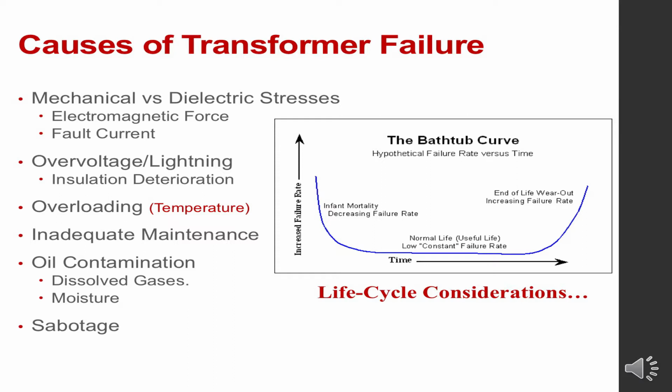So now let's get into the meat and potatoes on this particular slide. The first thing to cover is the differences between mechanical and dielectric stressors in the workplace. Now, I think mechanical stressors are sometimes overlooked by folks when we think about electrical hazards. And what I mean by mechanical hazards are literally the electromagnetic forces that develop when a circuit is faulted, when there's a short circuit in the system, or even when you're picking up a large industrial load. When a lot of electrical current flows in a circuit, like during a faulted element, there are electromagnetic forces that develop that produce physical forces that are so strong that it can literally take metal bus bars and twist them like a pretzel in a sixth of a second or so.